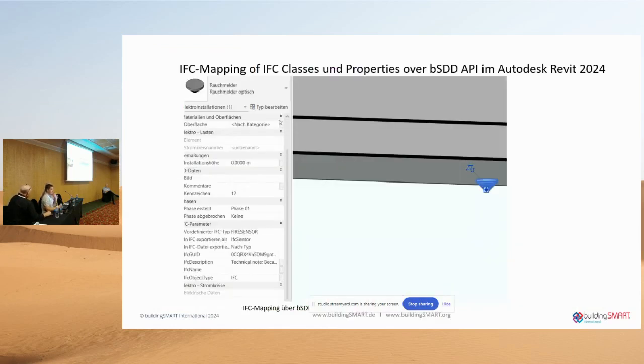We now have the possibility to use mapping tools, if we have some kind of new items that were not available within the buildings at the time, but Richard wanted to have new sensors, or to exchange or put in additional fire extinguishers. So we can have a federated model, and we can add them on top. And plus, as you can see, we map them properly. It's an IFC sensor, it's a fire sensor.